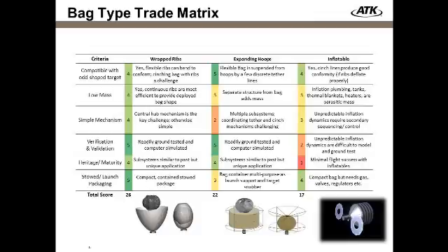The expanding hoops looks very similar to what Brian presented. The primary difference is that instead of inflatable tubes, we've used articulating booms that have very high strength, able to both deploy and retract. Again, we use 6 of these, 3 that come out radially, and then 3 that would come along axially with a kind of a scissors hoop around both the top and bottom, and then a lanyard deployed bag that would sit in front of that. Our concept in here was that the lanyard would then collapse or be pulled closer to that bag to bring the asteroid into a location closer to the satellite.